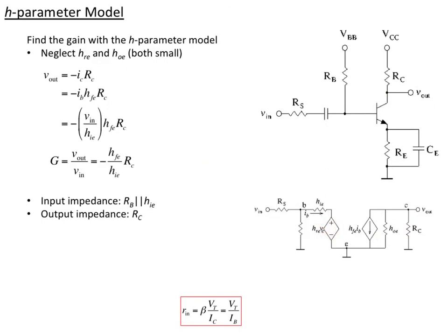So we're still only going to have those two components. These are going to be neglected, which means a short circuit there, and this will be gone, no conductance for that path. And so we just restate the gain we had before in terms of these new parameters, and before we had beta over the input resistance, we just relabel that as HFE over H sub IE.